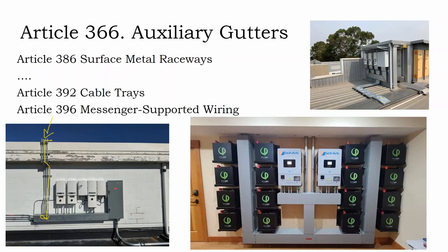So we could have used 2 sticks of conduit and had a nice smooth bend. I personally don't like using unnecessary LBs. Instead, we're not making 4 turns before we land on this LB, and we're not making 4 additional turns before we land on that LB.